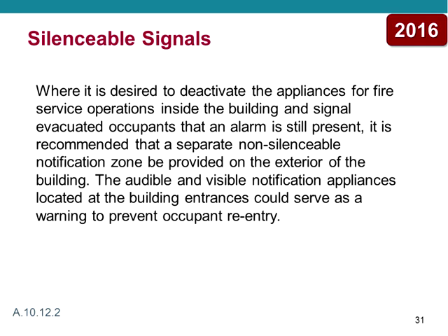And then the last change to Chapter 10 isn't really a change at all. It's an annex section that was added to clarify that it might be a good idea, when we use notification appliance deactivation, that we put some kind of signaling appliance outside of the space to let people know that they probably shouldn't enter when it's still operating. Because in current fashion, we typically will deactivate the appliances in the building.